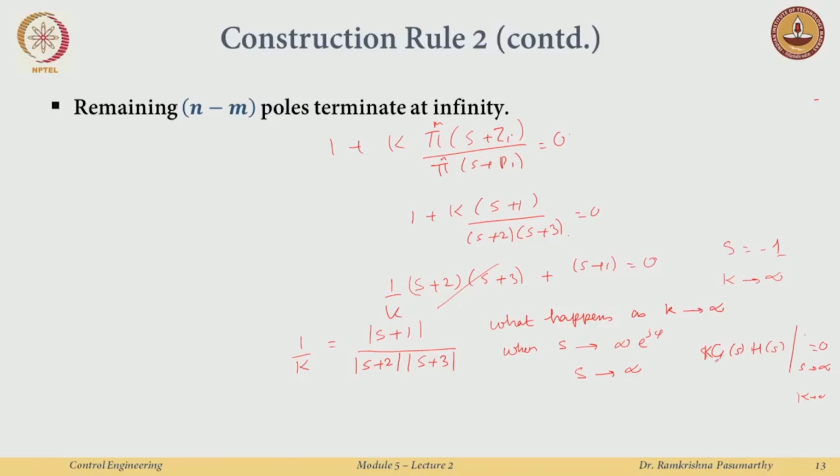Now, these are what I call zeros at infinity, because even at this value at infinity the value of the transfer function goes to 0, and that is the definition of a zero. Now, take the example we were doing the other day, 1 over s plus a. Similar thing holds here, and both the roots are now going to what we call zeros at infinity.